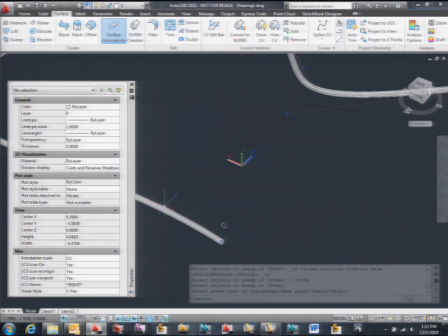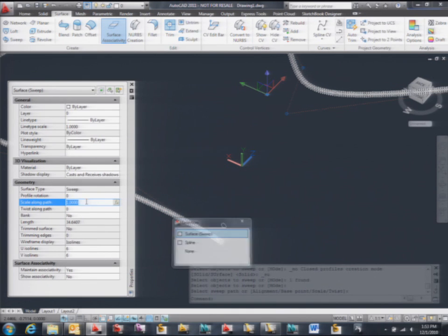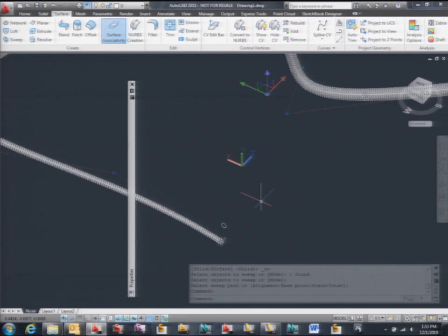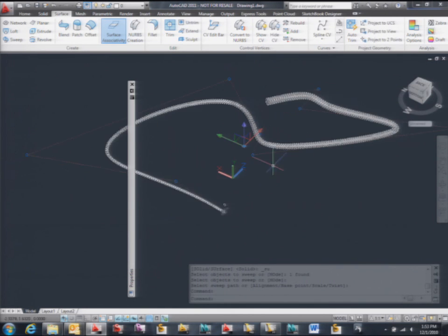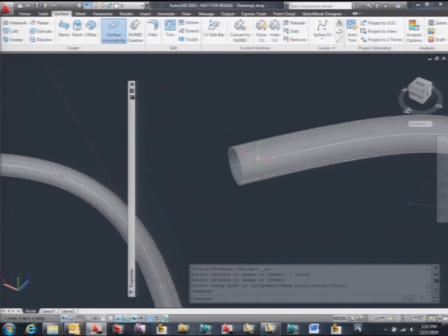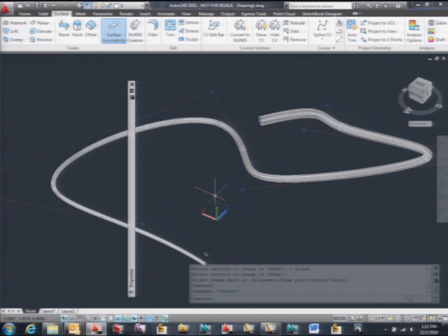Okay, and grab this guy. See, there you go. You see, the sweep is scaling along the spline. So for scaling, you need a first point and a last point. So let's say that you built this spline a week ago, or somebody else did it, and you just got the sketch, right? How did you know which was the first point? Again, go to Spline Edit, see the vertex, have a little cross. I mean, just a lousy little cross here. It was not easy to do, right? Again, no wonder why nobody used splines. So now we're making it much easier, right?